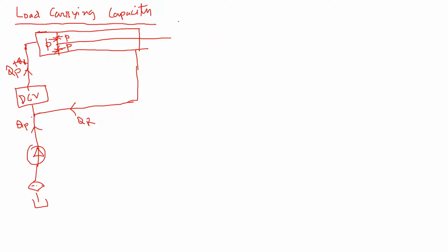So the force at the blank end is going to be the blank end pressure times the area of the piston, and that is acting in the right direction. And the force at the rod end would be the rod end pressure times the area of the rod end, which is the area of the piston minus the area of the rod.